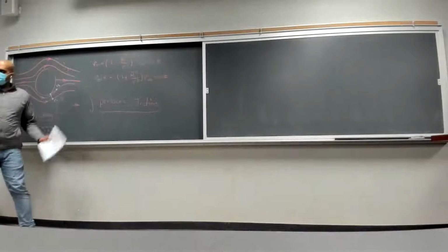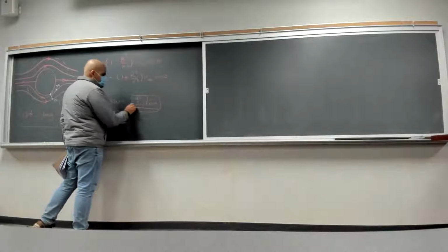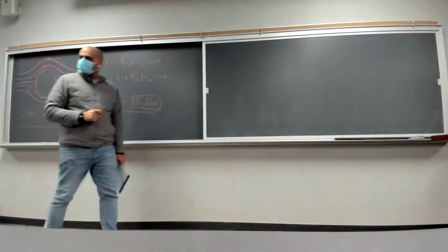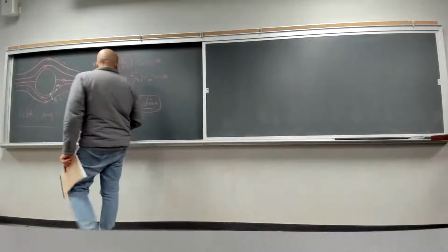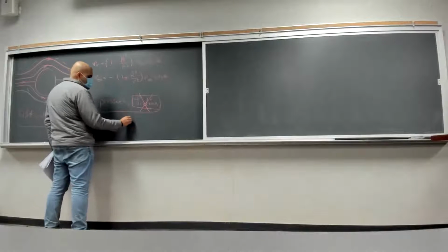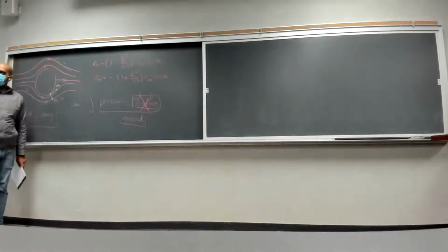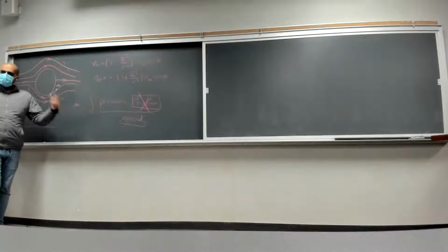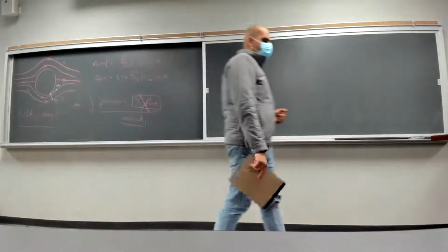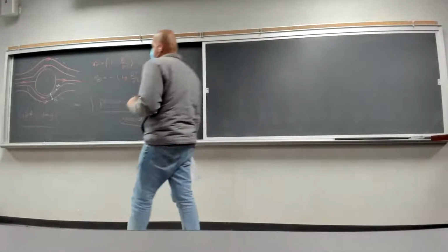Okay. Let's see if we can simplify this a little further. Do we have friction in this case? Exactly. The idea was we are mostly dealing with inviscid flow unless you are told otherwise. So we essentially have to find the pressure coefficient distribution, or pressure distribution in a more general term, on the surface of this cylinder.